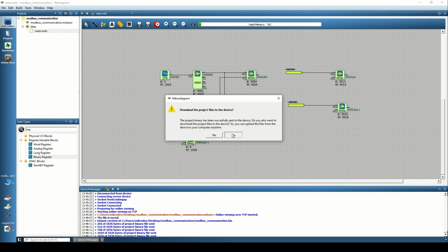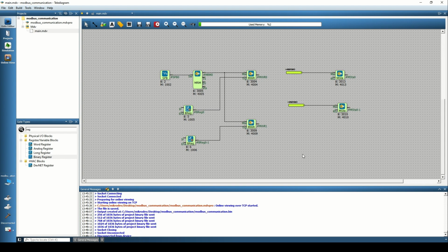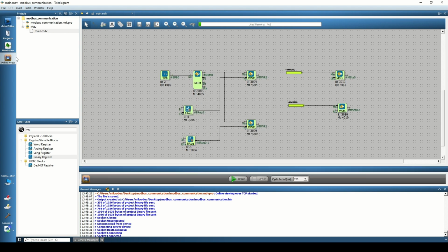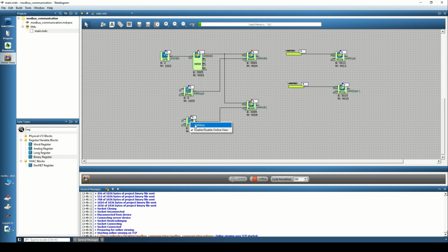Let's load this project to the device. We will see the status of the analyzers according to the connections. I'm starting online monitoring. Currently, let's first trigger an analyzer to read its data. The data came, and we saw that the MODBUS status reached a certain position. The other side was at 0 because I didn't send a trigger. I sent the first query again. This time, the status of the other ID device also became 1. Let me send another trigger.